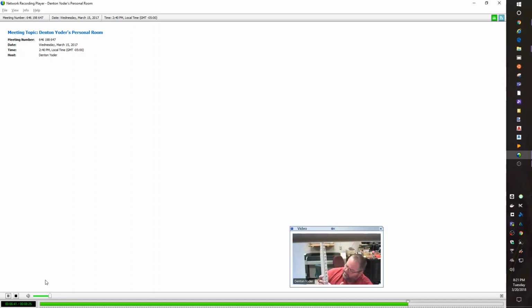The lowest number they see will be when it's perfectly perpendicular. So they'll see a higher number, lower number, higher number, lower number. Record the lowest number because that is the most accurate distance.